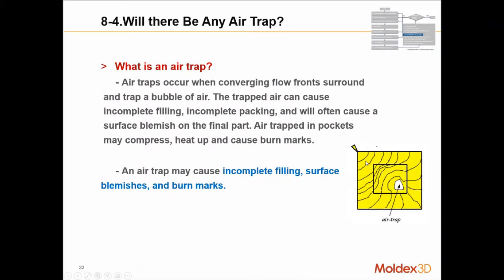In this diagram here, the outside perimeter of the part is pretty thick, and the inside rectangle is quite a bit thinner than the outside. So what happens is the melt will prefer to flow in the easiest to flow region, or the highest cross-sectional area region, which is going to be around the outside, and then it'll try to fill in the inside once it's done filling the outside, using the amount of pressure that it can.